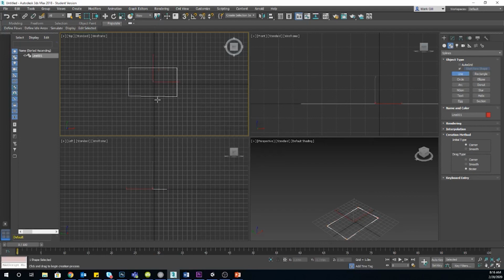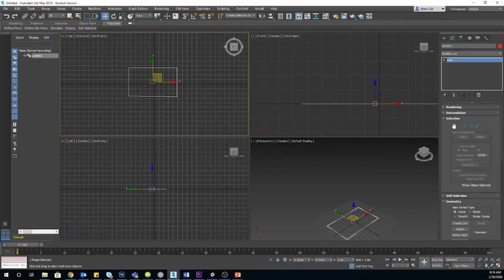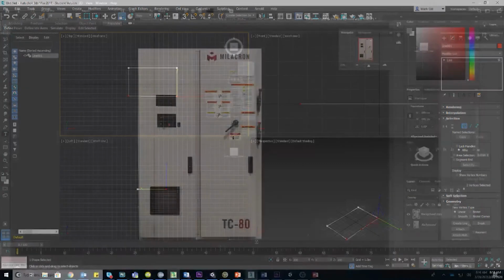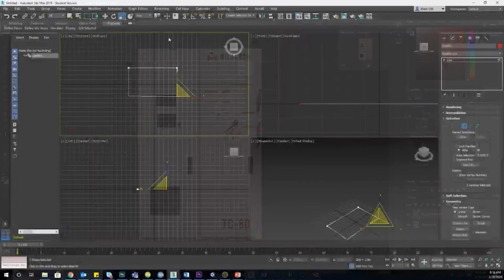Now, this last angle doesn't make a good right angle the way I drew this. So let's say I've got some situation here where I've got these two vertexes that don't quite line up. I can select both the vertexes, and I can go to the scale tool. And now by scaling on only one axis and dropping the scale way down between those two.